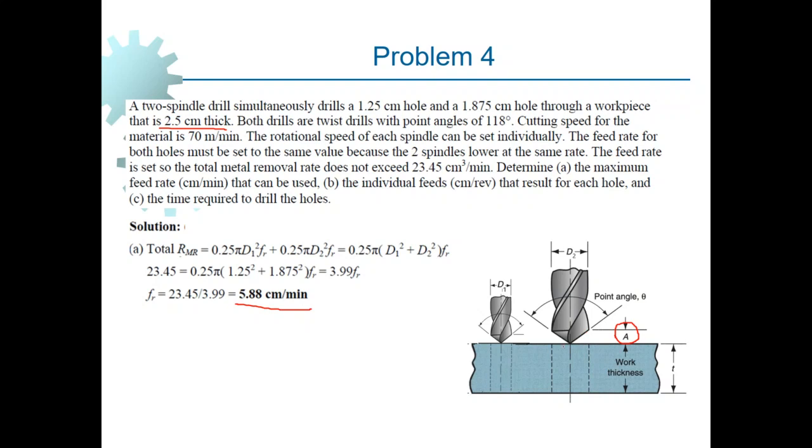How do we do this? Well, that's an interesting question indeed. There are two drill bits, and the allowance for this little one is different from the allowance for the larger diameter. The one that is greater is the one that should be considered, and of course it is the allowance for the larger drill bit, because they move at the same time up and down, and the extra travel for the larger drill bit is larger than the extra distance to be traveled by the smaller drill bit. So the distance to be traveled by the larger drill bit is the one to be taken into consideration.